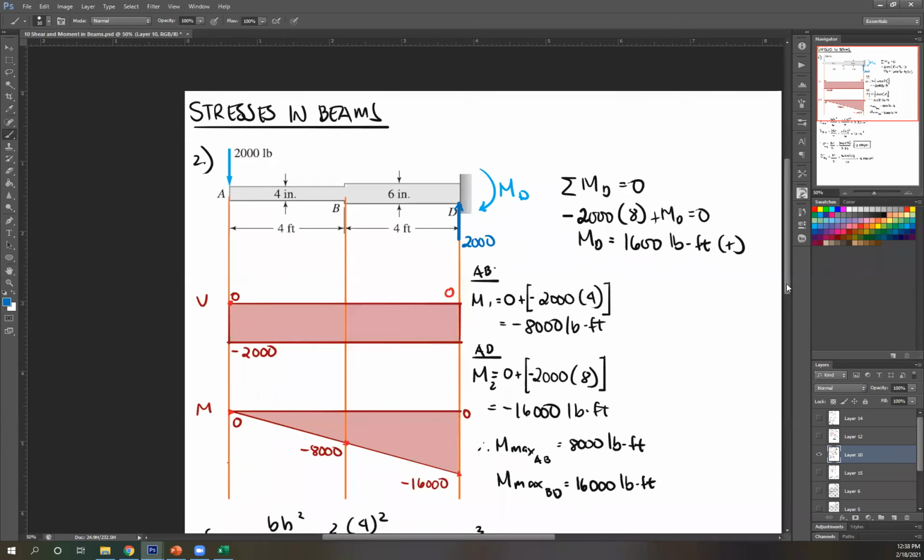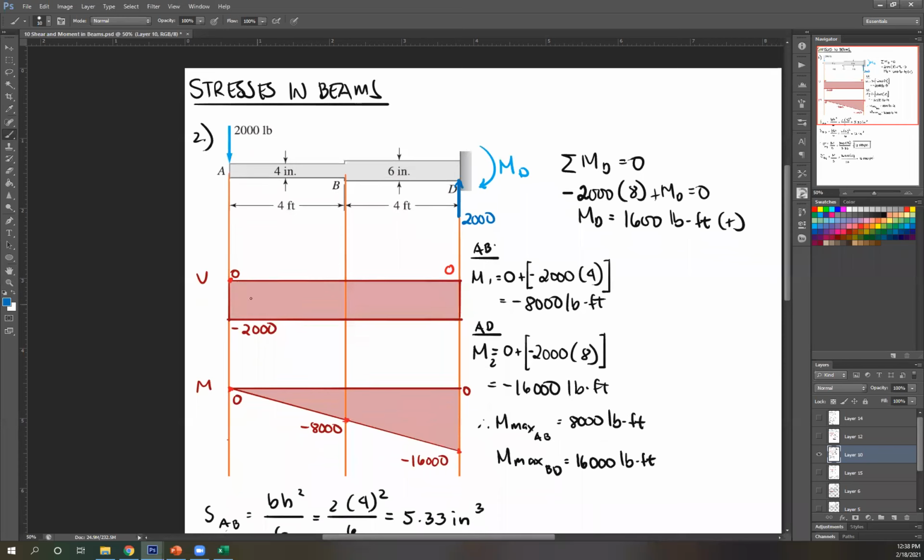Okay, correct shear diagram. Next, your moment diagram. So again, this is a free end. There's no moment there or applied moment, so you start at 0. Okay? You have an area that is below your reference line, therefore your slope is negative. This is a straight line, so one degree higher is a sloping line. Then, since there's no applied force or moment here, it's just a consistent line from A to D. So how much? So get the area of this.